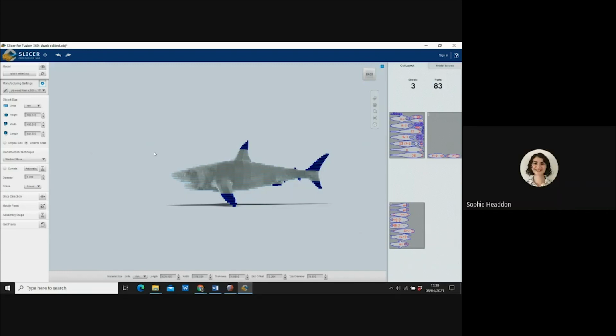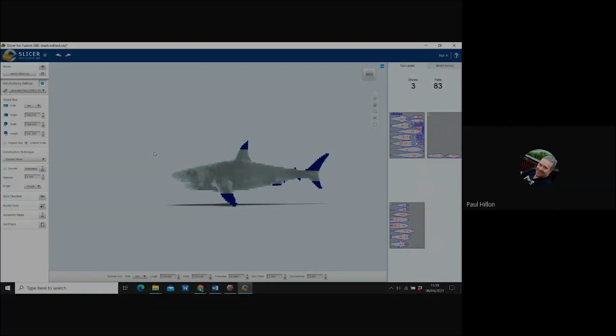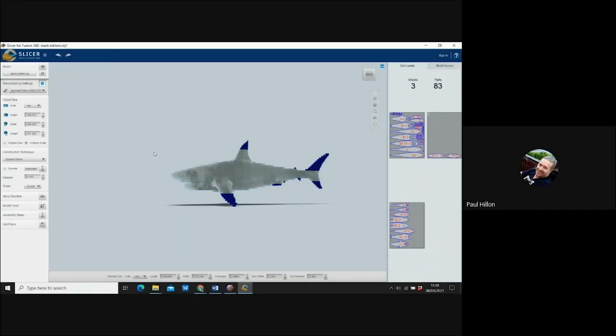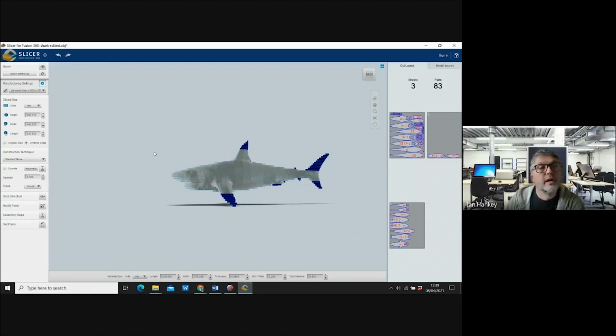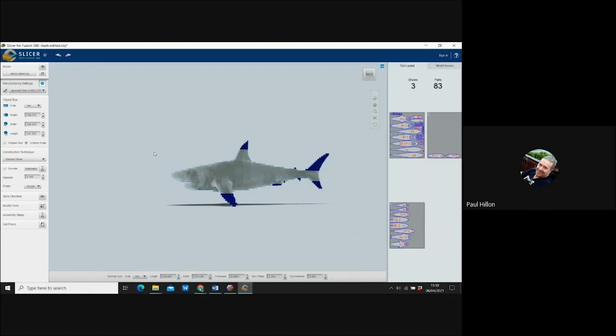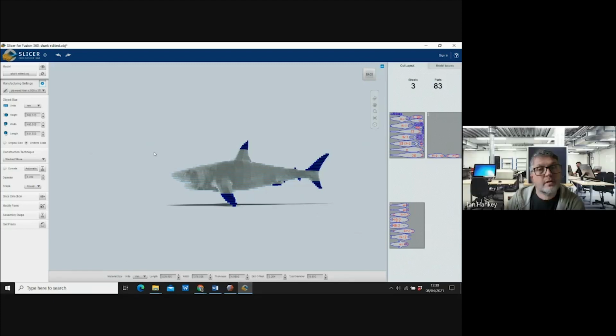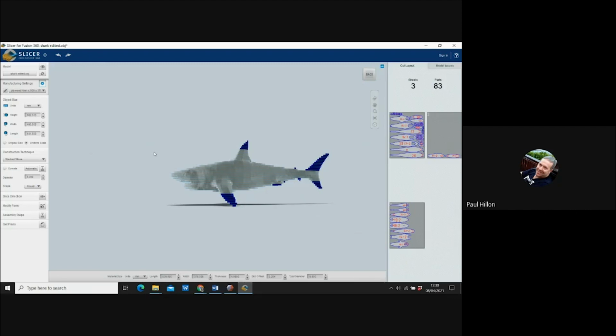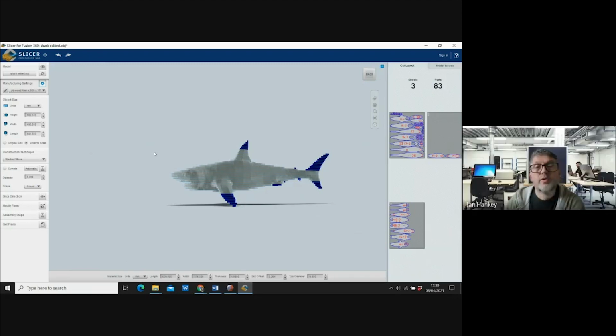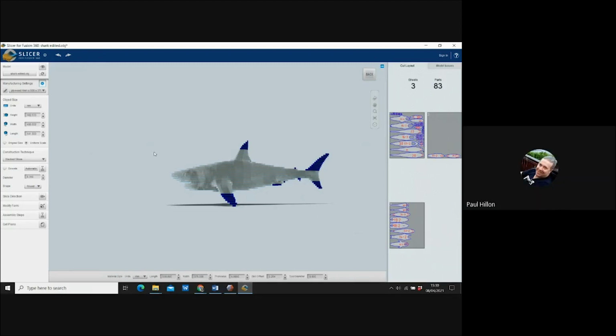It says, after the message, it was unable to process this model. Mohammed says the tool diameter is 0. I've got a similar problem as well. I was going to ask the question, when you put the plywood details in, and then you change the materials to make them fit your materials, and then you talked about the tolerance. Yes. Right underneath that, there was a tool diameter button. Okay. Let's have a look at that, shall we?